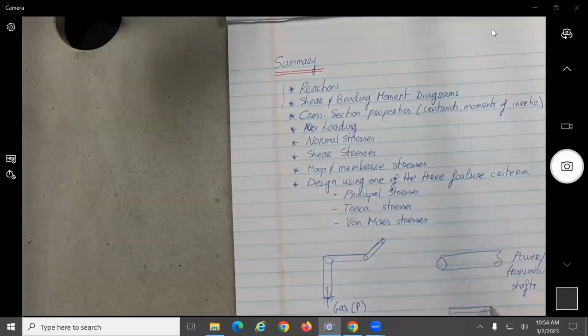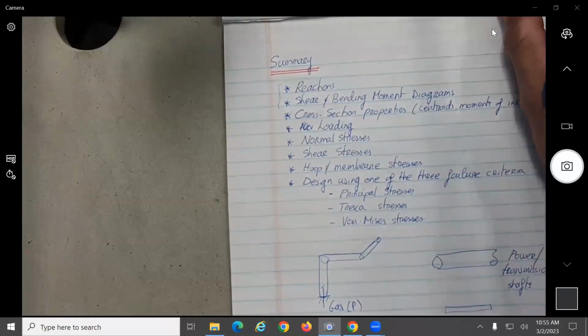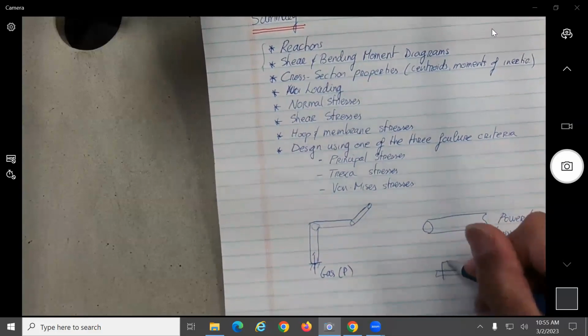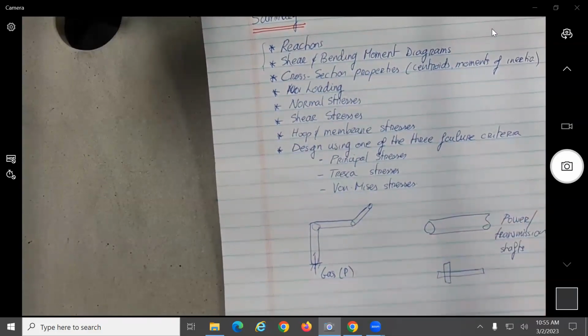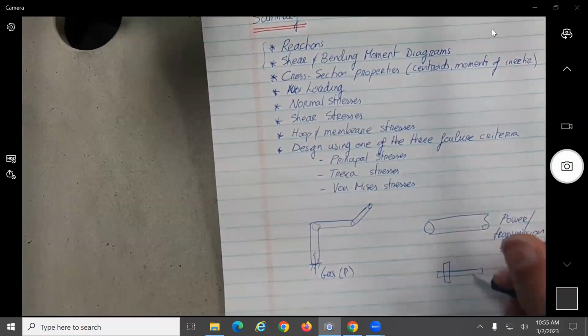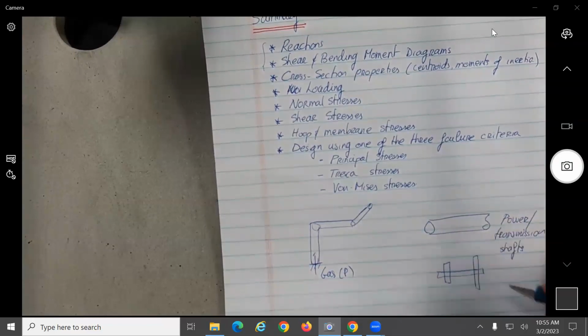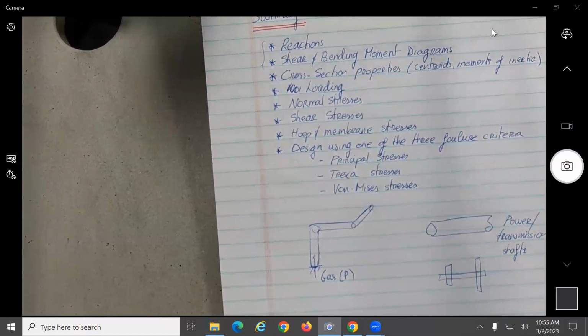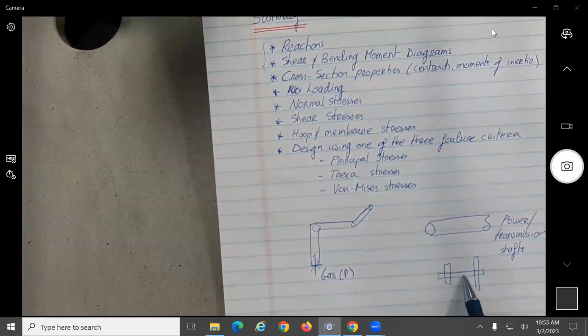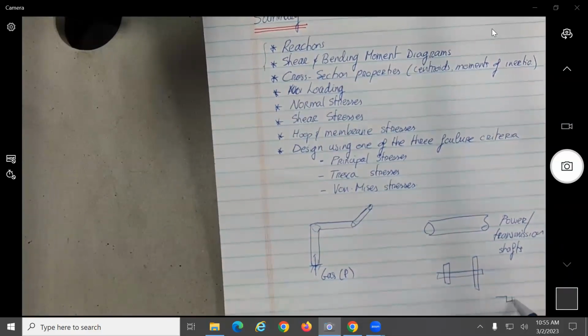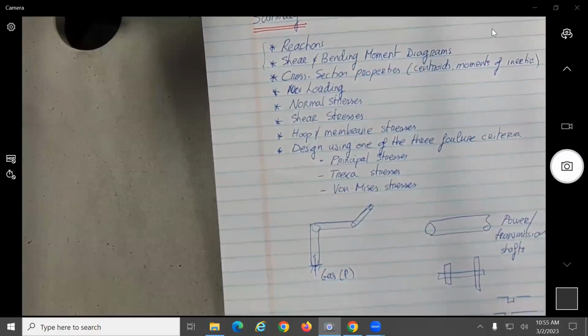If we look at very simplified, if you work here on the formula, I guess, or the Baja, what could you have? You can have one gear over here, no? One shaft connected to a gear, and here you have whatever, another one that is connected to the, no? So you know how to transfer the power. So what happens when you do the design of a shaft? How do you attach the gears to the transmission shaft? Anyone? Correct. So there you have on each side you have some keys, no? Correct. To connect this component.